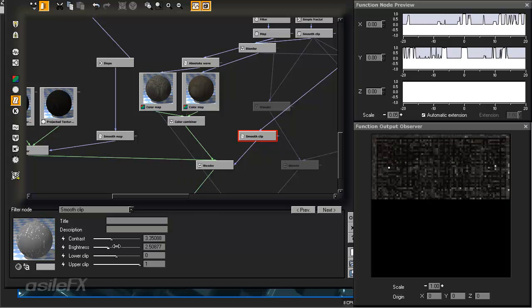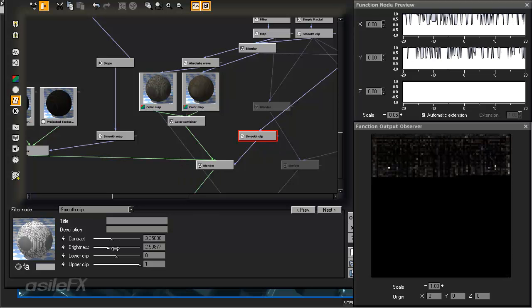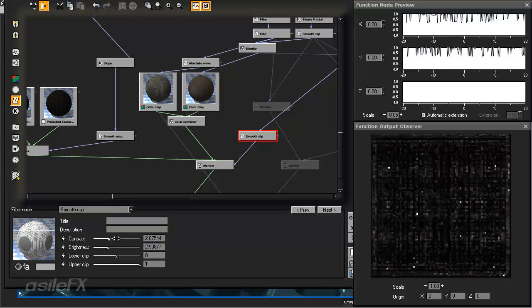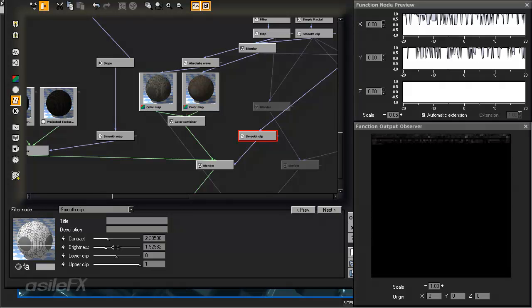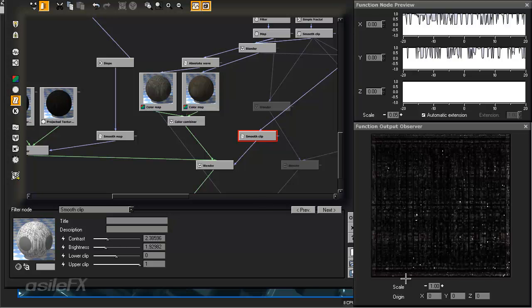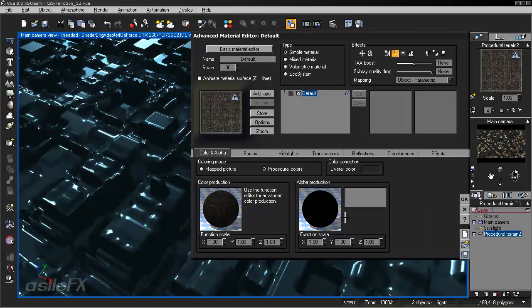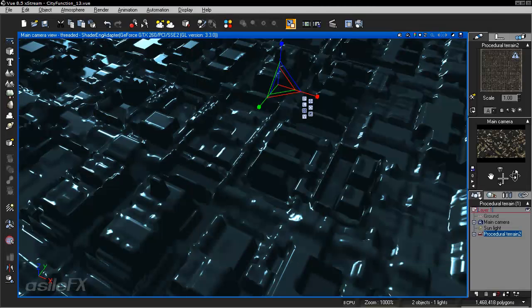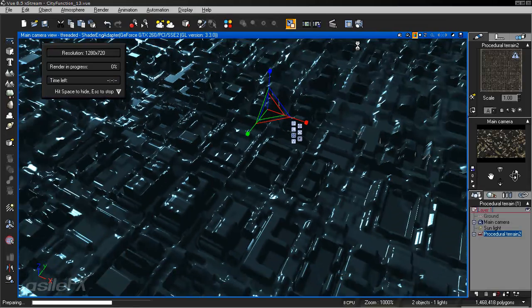And it looks like not nearly enough is white, which is why we're not seeing that texture map. It was a little difficult to see with that lower clipping set to -1 because those light gray values were just blending in a little too much. So we'll set this contrast to 2.5, set the brightness to 2, and that should give us a little bit of a better blend. And we'll zoom out and take a look.